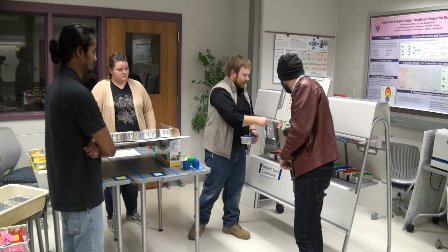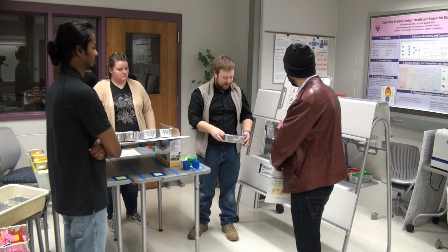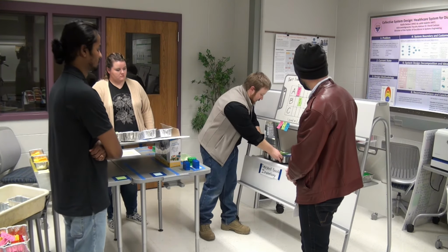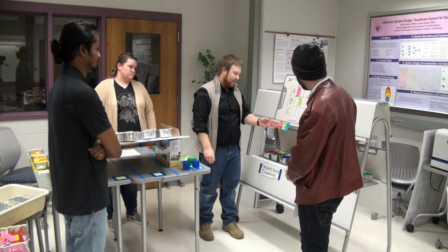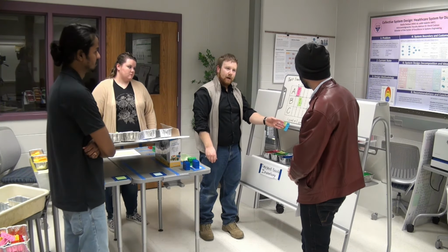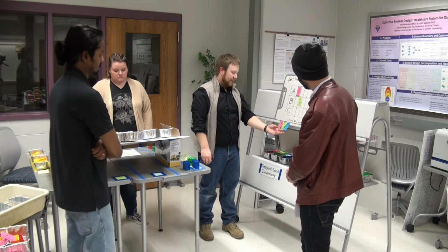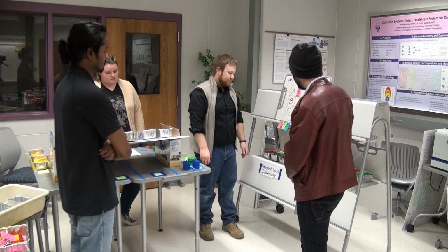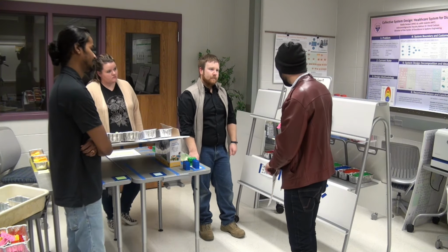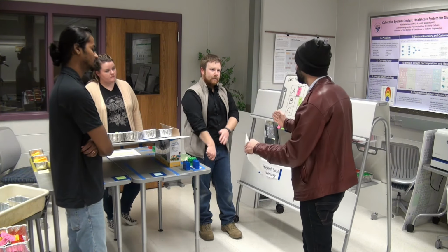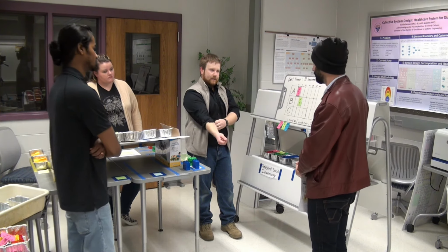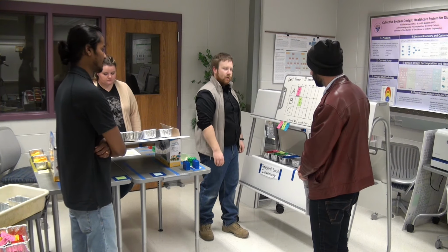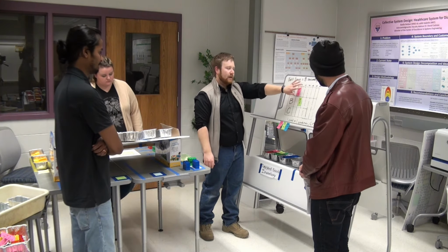And the Kanban cards keep piling up. And so by the time I'm done with this one and I replenish it, I am back to here, and I have what's called a Kanban pileup. And this is the indicator that I am not producing to takt time. So that means every time you have a card in a pileup, you can identify the disruption right away. Correct.